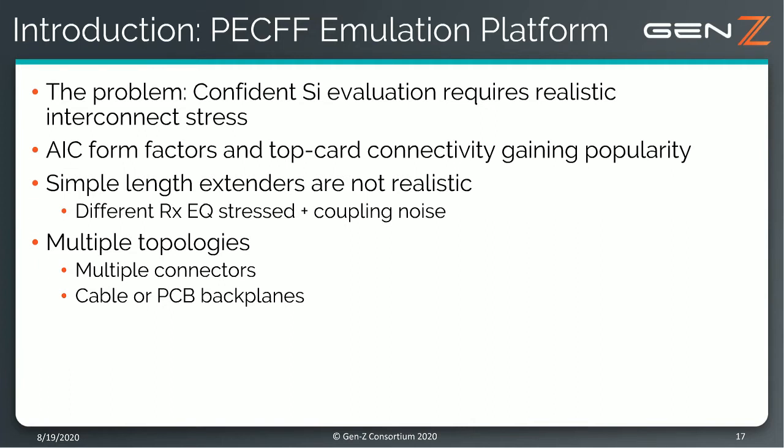And what we said was, typically the simple length extender that a PHY developer might use in the lab is not realistic enough, meaning a single long trace doesn't include the reflections or the crosstalk that a real system would experience, and one is interested in that to properly stress their equalization, do a proper lab validation, and test a product.